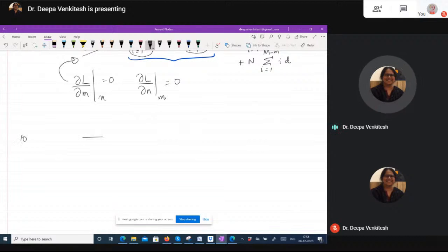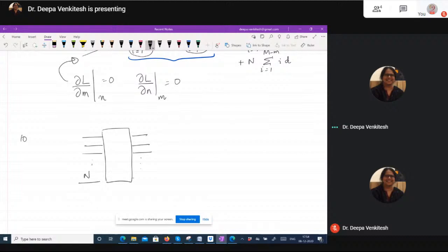So it's an n by n coupler. You have n input ports and n output ports. If you give power from port 1, the insertion losses are given. Find out the total excess loss. Now, the regular coupler loss, we saw, is minus 10 log 1 by n. But in addition, there is some loss because of the irregularity or non-ideality in fabrication, and that is what gives rise to this excess loss.